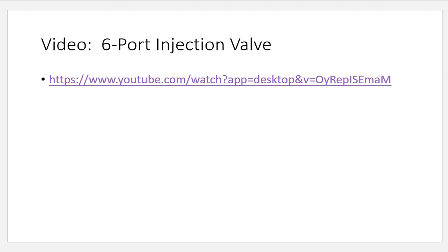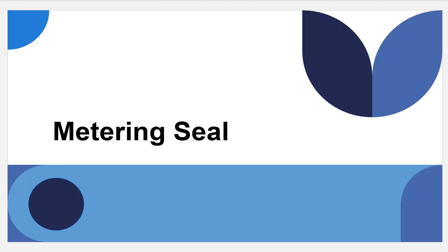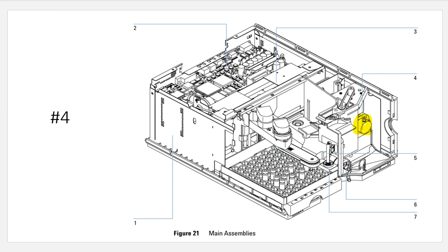Now, while we are talking about this discussion, we've already mentioned it, there is a seal in the metering device. That analytical head, or that metering device, again, that's the stainless steel piece up here to the side, that has the piston in it, that has a seal in it, and we want to make sure that it actually is sealed leak-free, so that we can get that nice suction that we want out of that system to pull our samples up and out of those containers.